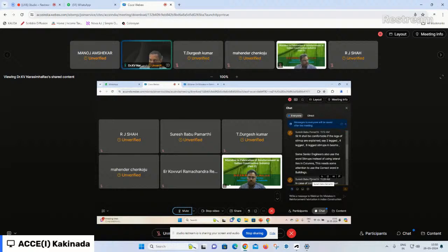is important, sir. Suppose you are considering it as a basement wall, whether you are considering the plate supported on the three edges or the plate supported on the two edges, or you simply design it as a cantilever stem wall, that is important, or whether you consider it as a plate supported on the four edges. That is, within the building frame, you are providing the basement wall. That is in the form of some sort of earth retaining structure you are providing.